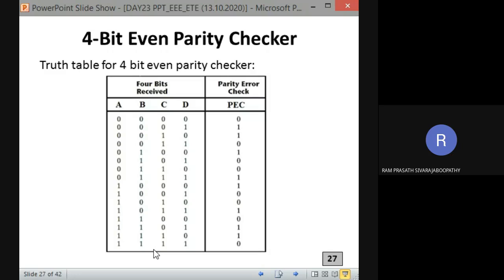Okay, Srihari? See, when you are transmitting a small number of bits, like 8 bits, we can go with a parity bit. Because when you are transmitting some 8 bits, the probability of error occurrence is very, very less. We are assuming for small data length, for small messages up to 8 bits, we can go for this parity code. If it is beyond 8 bits, we can use some other method. I've already told you, Hamming code, CRC, many methods are there. Shall I proceed?